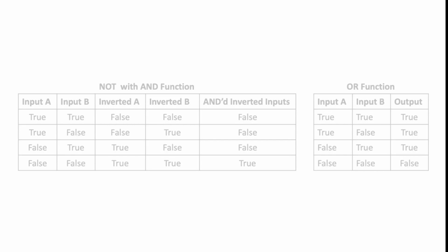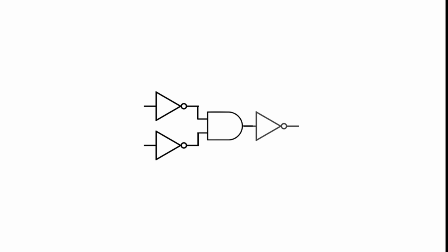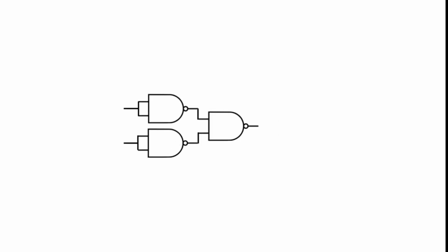All we need to do is invert the output with a NOT. So instead of ANDing the inverted inputs together, we want to NAND the inverted inputs together. Here's the logic schematic for the OR gate. Notice that we can build the circuit for this schematic with a single 7400 chip and still have an unused NAND gate.